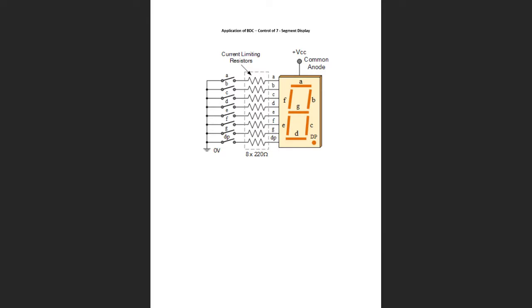So you can see by closing certain switches, and again, this is not really done by switches. This is actually controlled with another chip or transistors, but just for ease of understanding, you can close certain switches, and you can actually get any of the number digits 0 through 9. If I close all switches, then I'll get the number 8, right? I have an 8 there.